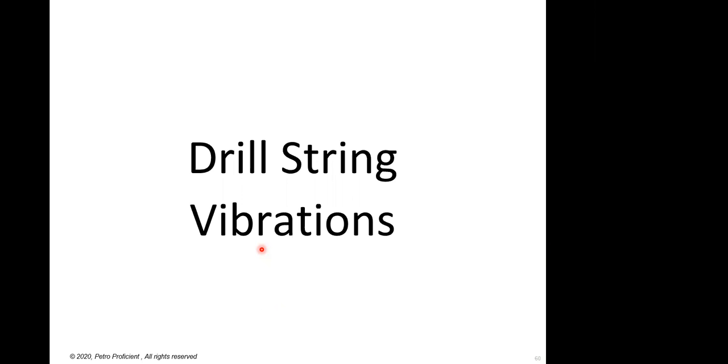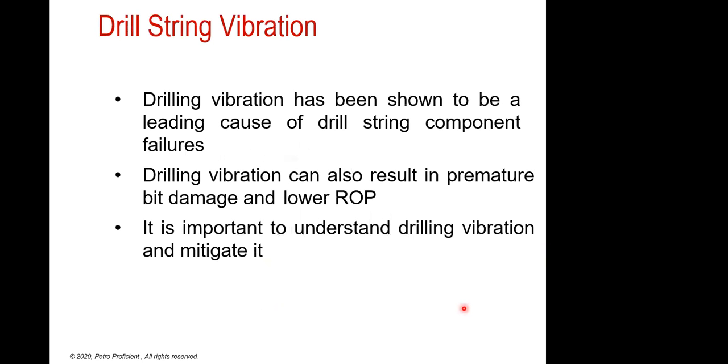You'll be just rotating in one place, causing a severe loss to the oil company, because of not being able to achieve the desired ROP or desired drilling depth. These are the points that are important to analyze as we go. As I said, they are one of the major causes of failures of drill pipe. Drill pipe receives a lot of cyclical load, makeup, breaking, and so on.